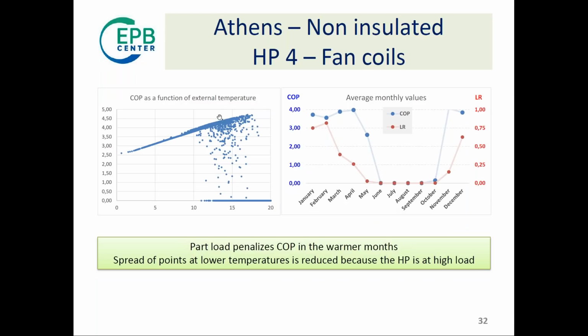Same type of graphs, and here you see that you have the main curve, and here you have some points where you have a really low load, and the same representation of the load factor of your heat pump, and here the result for your monthly COP. And again, it is a half season. Well, actually, this is concerning, and this also is important when interpreting data. Sometimes you have a high percentage, but it applies on a small amount. And this we have to remember.